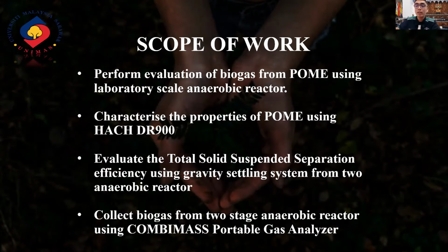So the scope of work in order to achieve the objective is to perform the evaluation of biogas from POME using a laboratory scale anaerobic reactor, which is a 2 stages anaerobic reactor. And then next, in order to achieve a specific objective, is to characterize the properties of POME by using water analysis, which is using a HACH DR900 provided by the chemical department of Faculty of Engineering UNIMAS.